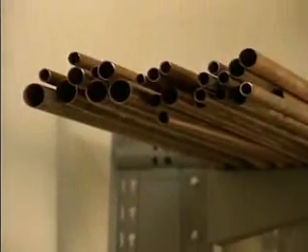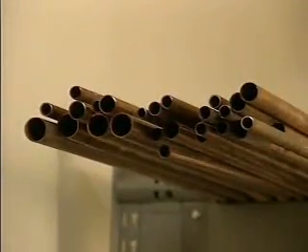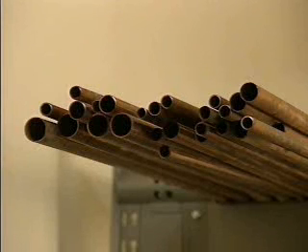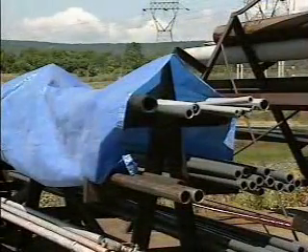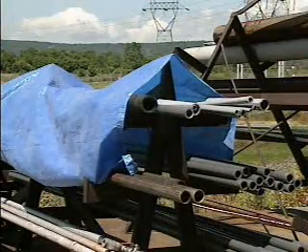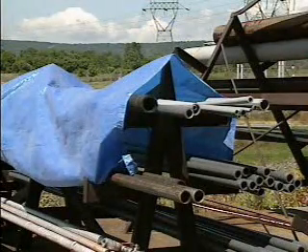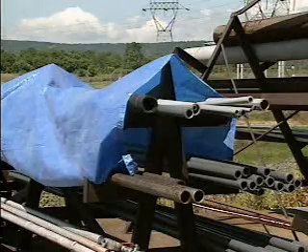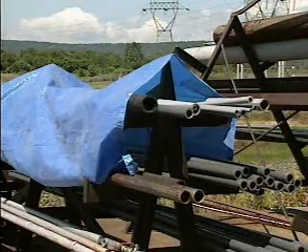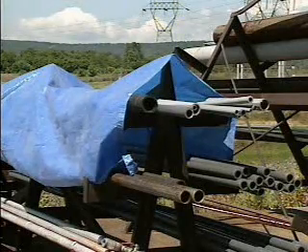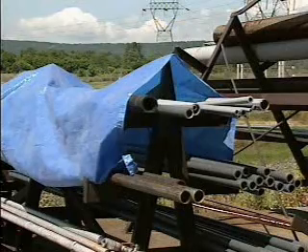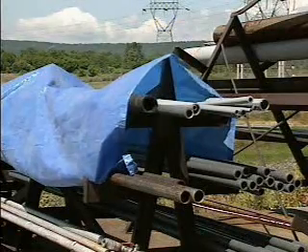Be sure that pipes made from different materials are stored separately. For example, a number of aluminum pipes can be stored together, but they should not be stored with pipes made of copper. This makes pipe selection easier for maintenance personnel. Store pipes indoors when possible. Cover pipes stored outdoors with a tarpaulin or other suitable material. This will further guard against corrosion and contamination from sunlight and other environmental factors, such as moisture and changes in temperature.